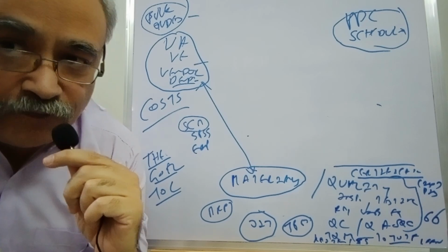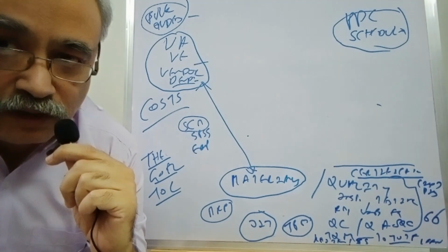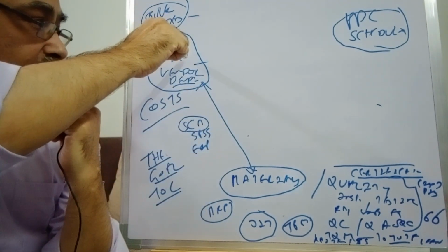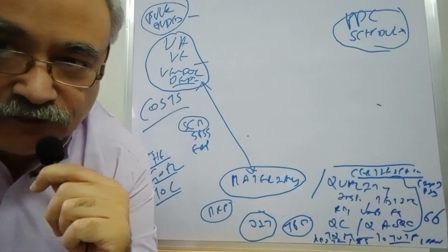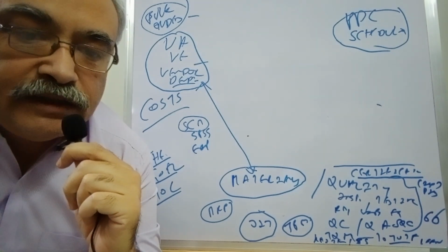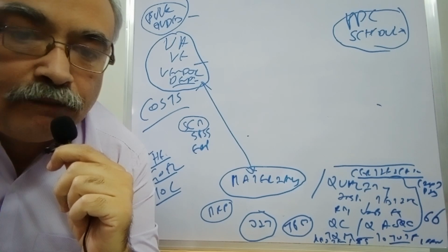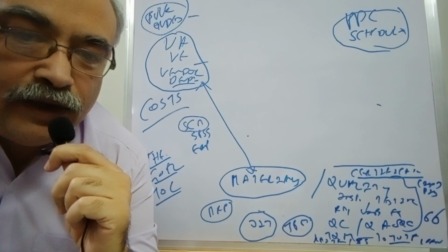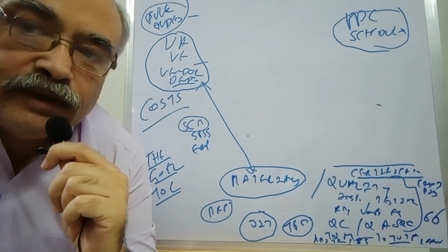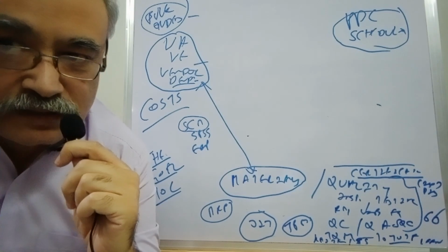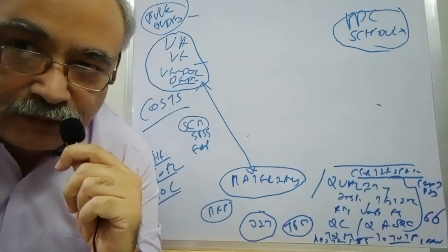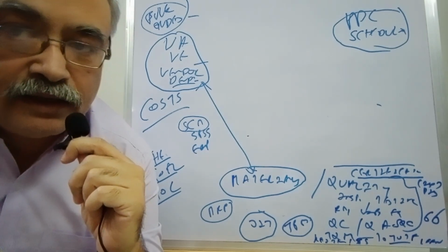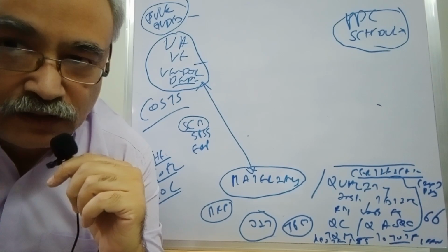We might also have to develop vendors for some special parts which are not available in the market. We also can discuss value engineering and value analysis, VE and VA, with the vendors. Value engineering is when he's supplying a part but we don't need those features, so we can ask him to reduce those features or knock out those features so his cost goes down, so he can sell it to us cheaper, keeping the same profit margin, and our job is done. We don't need those extra features. That is engineering at the design stage when we are discussing the part requirement with him.